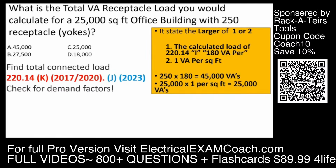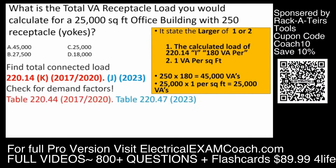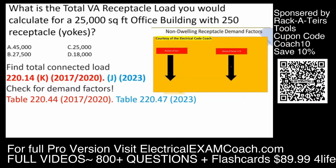So we check for demand factors. That leads us to table 220.44 if we're in the 17 or 20, and table 220.47 if we're in the 2023. Same information, different title. When we get there, we're going to see it's very similar to table 220.42 and 220.45, depending on what code cycle we're in, that we're going to start on the left-hand side, and it's going to tell us our portion of VAs, and then on the right side, it's going to tell us our demand factor in percentage.